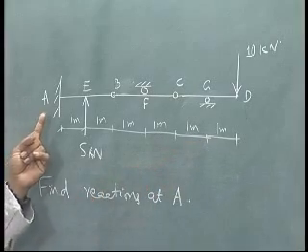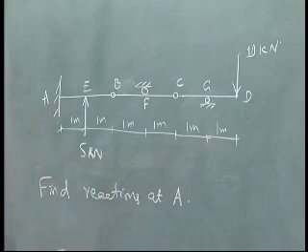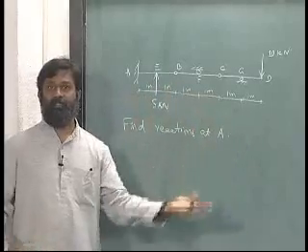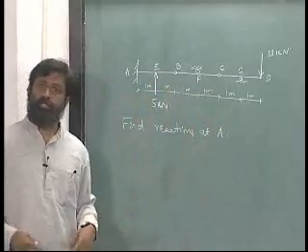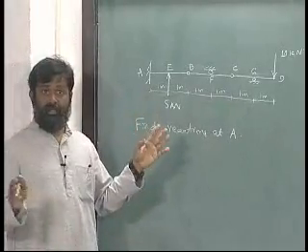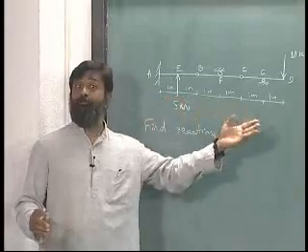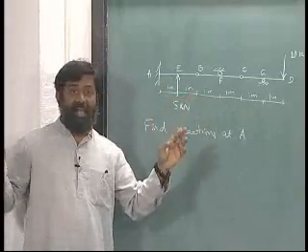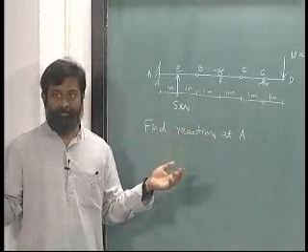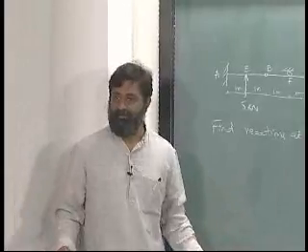Say I need to find out the reactions at A, that is the problem given to me. Okay. And we have to use virtual work principle. We can use other principles also. Mind you, in virtual work principle one of the advantages I will get is I will only have active forces participating as long as I have kinematically admissible displacements. The moment I have kinematically admissible displacements, it becomes easy, alright.